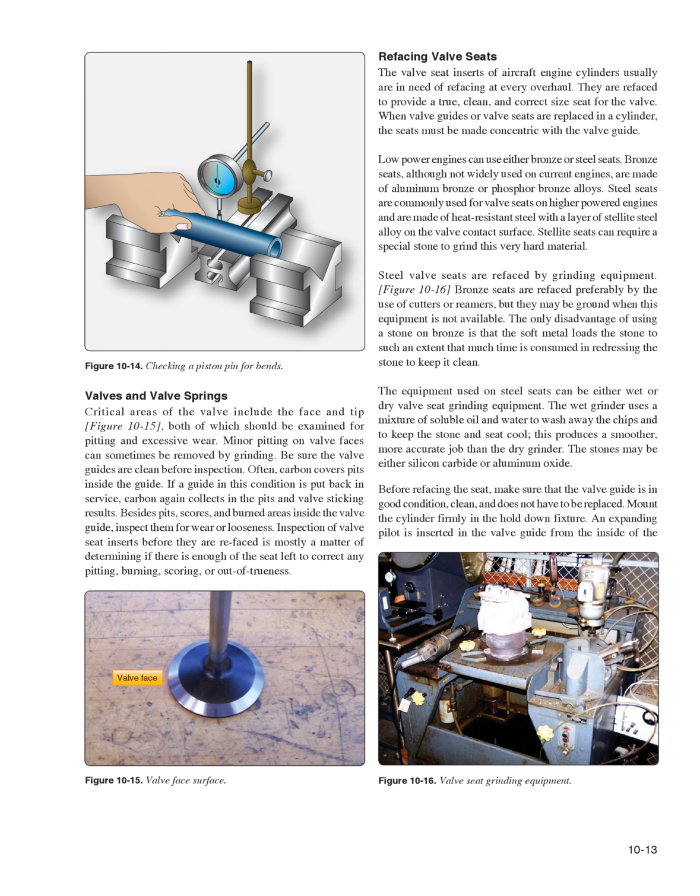Inspection of valve seat inserts before they are refaced is mostly a matter of determining if there is enough of the seat left to correct any pitting, burning, scoring, or out of trueness. Refacing valve seats. The valve seat inserts of aircraft engine cylinders usually are in need of refacing at every overhaul. They are refaced to provide a true, clean, and correct size seat for the valve.